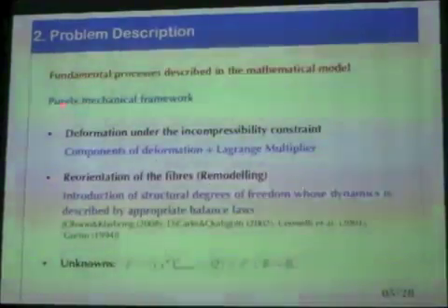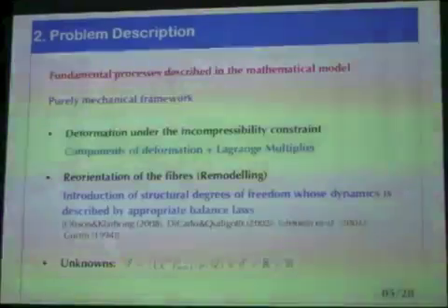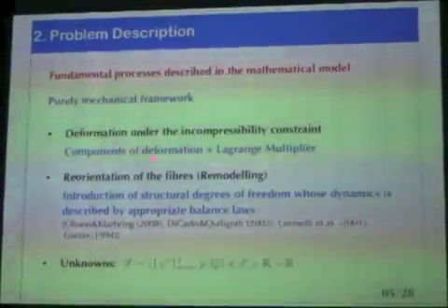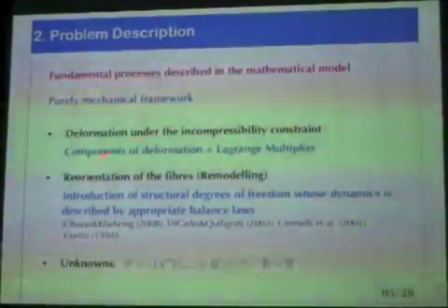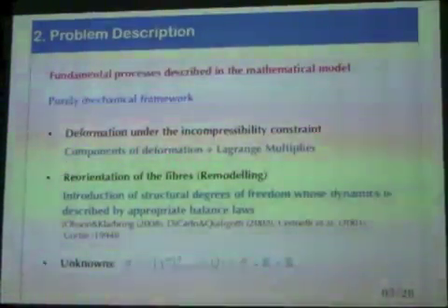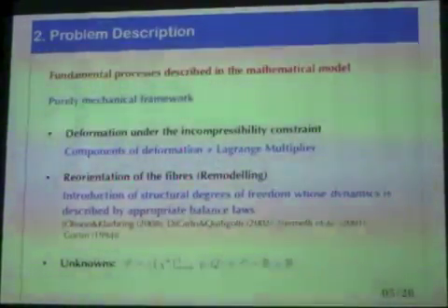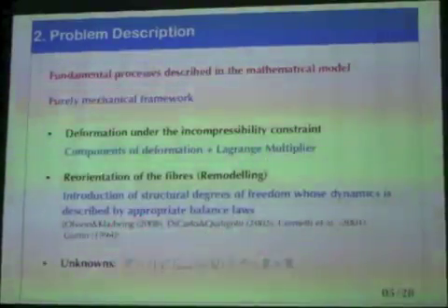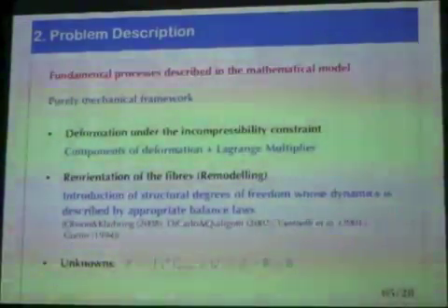We put ourselves in a purely mechanical framework, and what we would like to study is the deformation of this composite, as I said, under the assumption of incompressibility, which means that we have to compute the components of the deformation plus the Lagrangian multiplier expressing pressure, and the reorientation of the fibers, which we call remodeling in this context, by introducing a structural degree of freedom whose dynamics has to be described by appropriate balance laws.